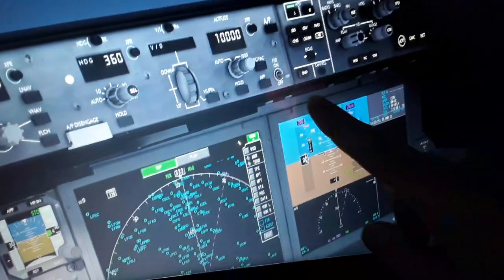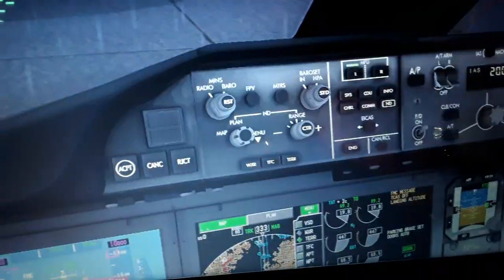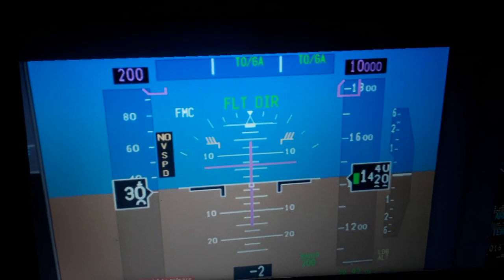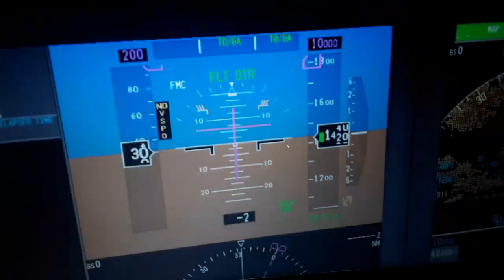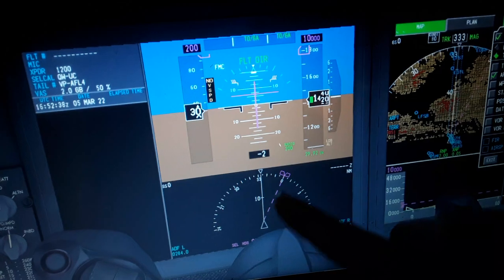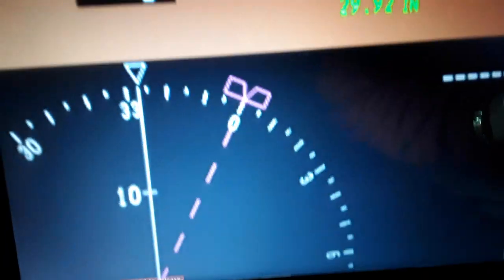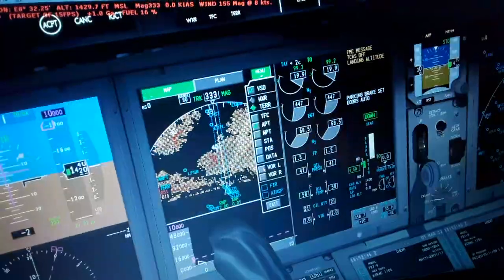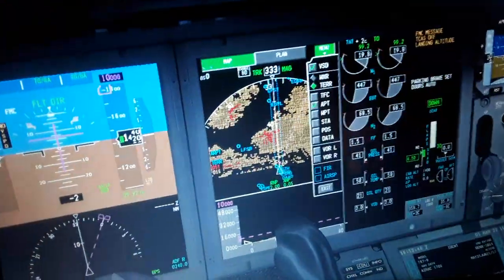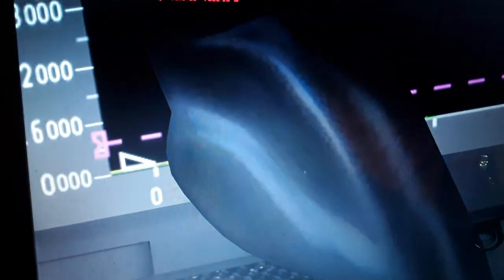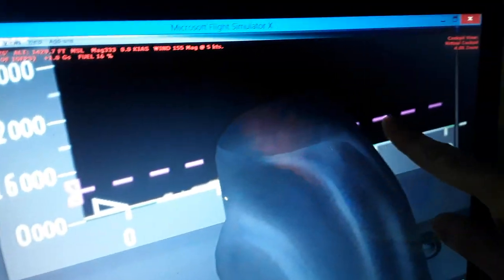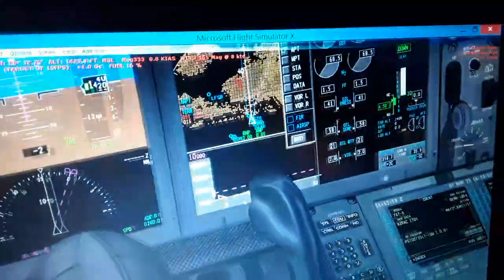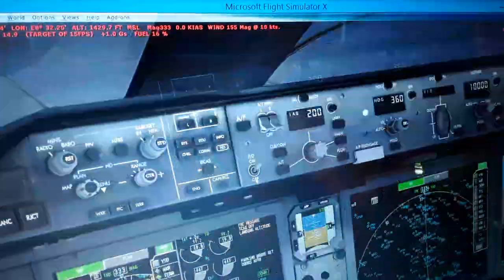So we have the same here in the primary flight display, both of them, both sides. So you can see here 200 knots, 10,000 feet. You will see later different values, and also the heading is 360 degrees over here, or zero heading. So you can see also in the vertical display here we have also 10,000 feet selected. Right now this magenta purple line, we're going to be flying higher, so you will see when we're leveling off in climbs or in descents.